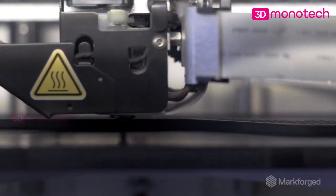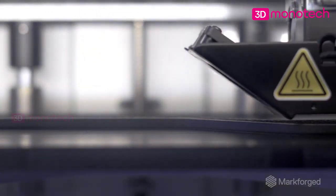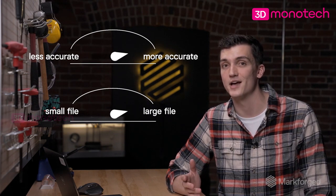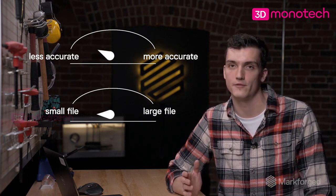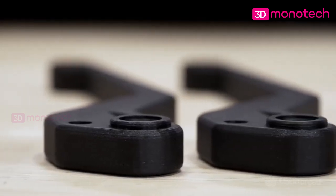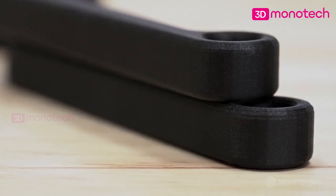You may be asking yourself, why would the settings I use to make an STL impact print quality so heavily? Well, the STL mesh directly informs a slicing program on how to make the printer's nozzle move around. STL export settings feature many adjustments that allow you to either closely match the geometry at the cost of increased file size, or to reduce file size by sacrificing accuracy. Many engineering parts have at least some curved surfaces designed into them, which are especially subject to visual defects when they get approximated by a relatively low number of triangles. In short, if you don't nail your STL export settings, your parts could wind up looking something like this.